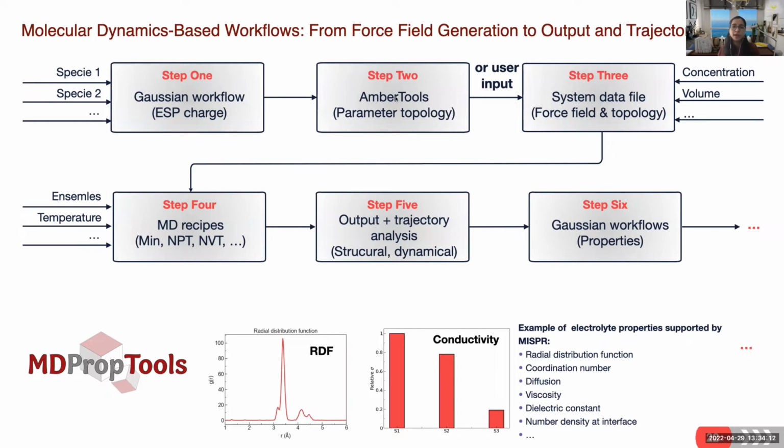But as I mentioned, the force fields are very important for the accuracy of MD simulations. So the workflow is quite flexible. The user can provide their own force field parameters or also take parameters from our in-house database. The next step is where we generate the files, which includes the topology and force field information. And then the user can specify the concentration, ratio of solvents, different mixtures they want to use, temperature, volume, etc.